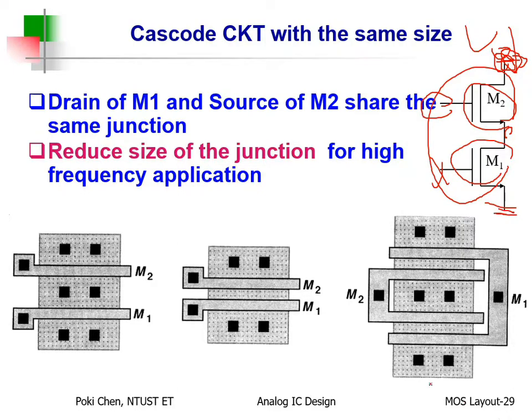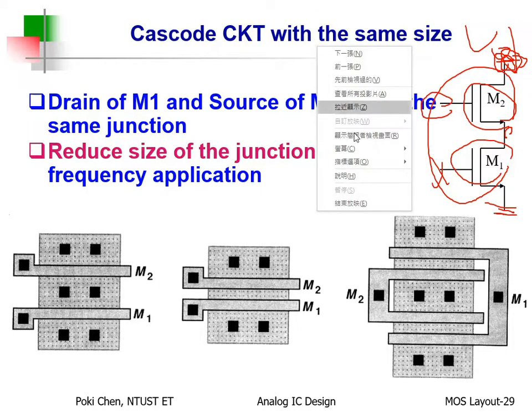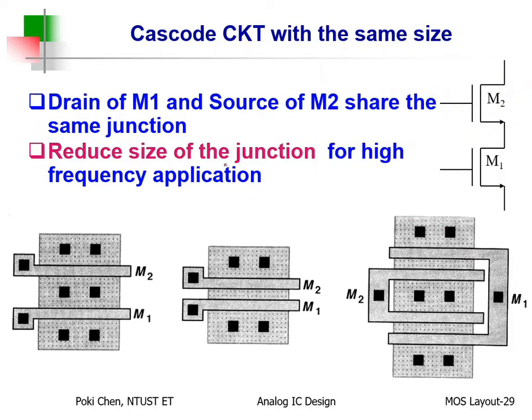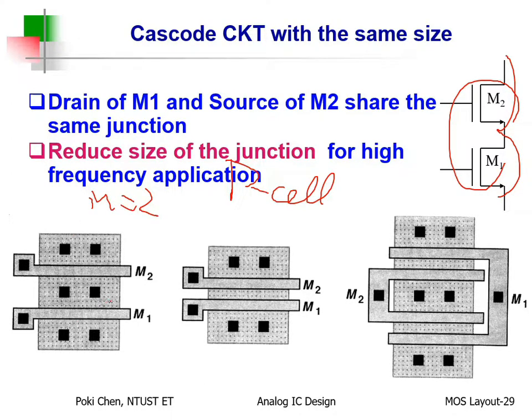But you guys are so lucky. I mentioned already, you have the so-called P cell. So more often than not, if they are the same size, they can be stacked. Just like, I told you, 1, 1. Then you will have M equals 2. Automatically, the EDA tool will help you to generate a pattern like this.